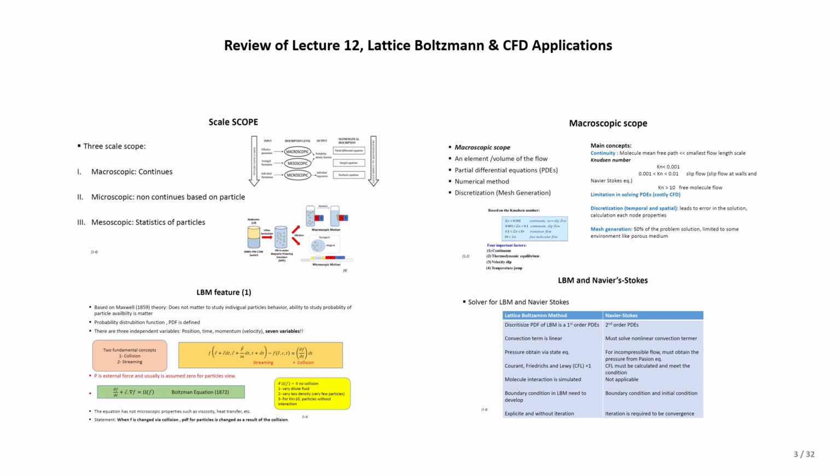the dominant feature is based on the energy transfer between the large eddies, and the viscosity doesn't matter too much, so it's required to specify the viscosity for the lattice Boltzmann model. However, for the small scale, the viscosity is the dominant player in the flow field.